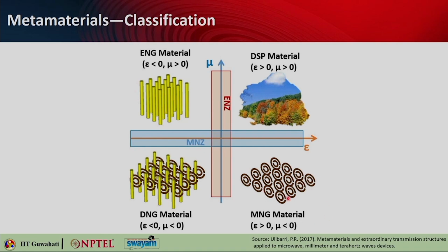Similarly, you can have an array of double split ring resonators, and they define the negative permeability. So this is also not a natural material, but using this kind of structure you can obtain negative permeability. These things people have shown mostly in the microwave region, because the size of the constituent materials, the meta atoms, is easy to handle. They are in, say, millimeter or centimeter scale.